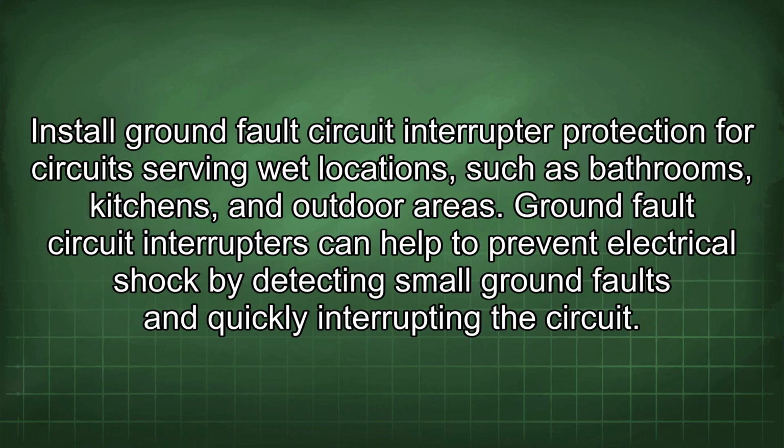Install ground fault circuit interrupter protection for circuits serving wet locations such as bathrooms, kitchens, and outdoor areas. Ground fault circuit interrupters can help to prevent electrical shock by detecting small ground faults and quickly interrupting the circuit.